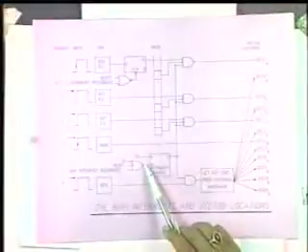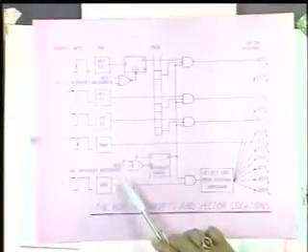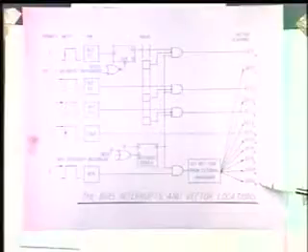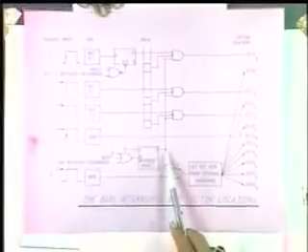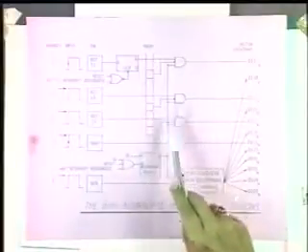that I have a flip-flop which is basically called the interrupt enable flip-flop. This flip-flop gets set when you execute an interrupt enable instruction, and then it gets reset when you disable the interrupt or when any interrupt is acknowledged. Now, so far as the interrupt is concerned, it has to provide the vector addresses as mentioned here, and this set of AND gates, what you see, is basically enabled by the interrupt enable flip-flop.